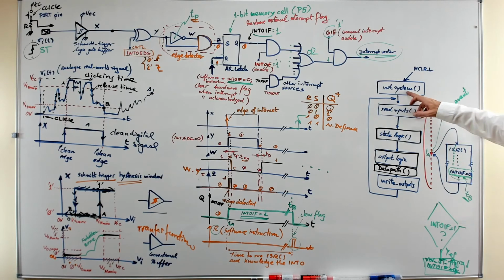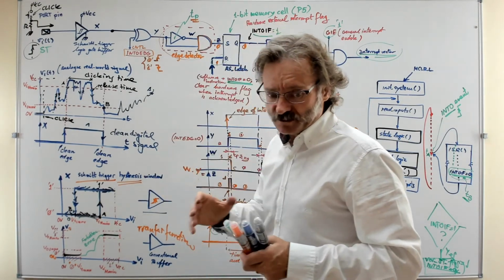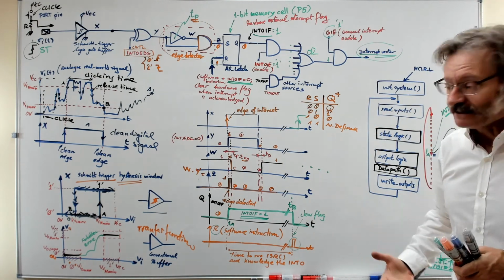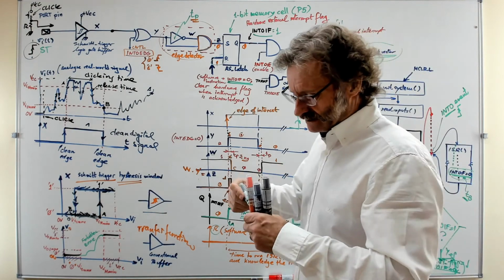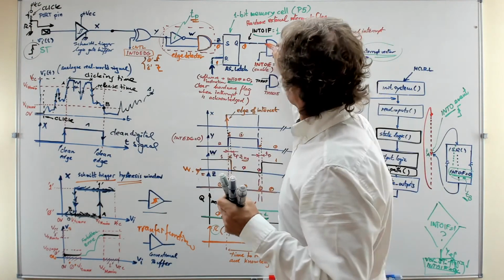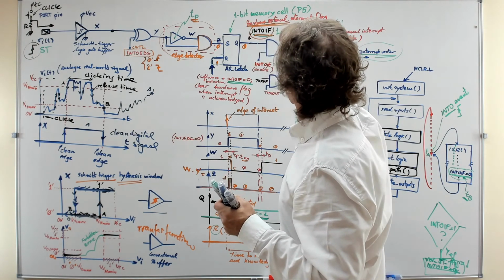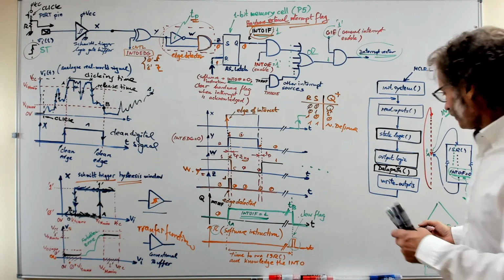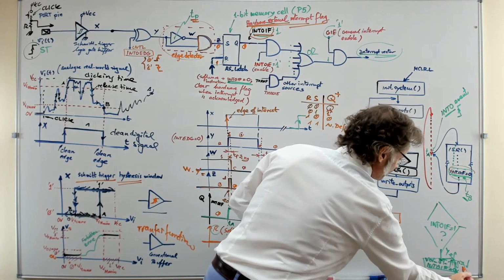So we will configure in the init system some of these values to prepare and organize the possibility to jump to the interrupt vector, and then in the interrupt vector itself we will talk about cleaning the hardware flag. So, to finalize this explanation, we will talk about this external interrupt 0 interrupt flag as a hardware external flag, because we will rather prefer to talk about the other one, the one that is set here as well, as I noted here.